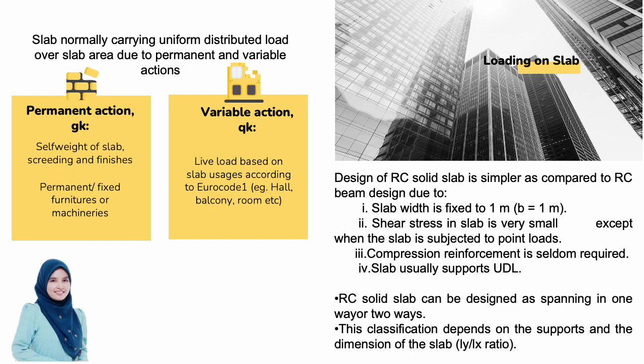So this fits with simplifying the design process because you don't need to consider variable width as you might with beams. Number two, the low shear stress in slabs. Solid slabs typically have low shear stresses compared to beams. This is because the load is distributed over a wider area in a slab, leading to a smaller shear force, except in cases where the slab is subjected to concentrated point load. So the simplified shear behavior can make the design process less complex.